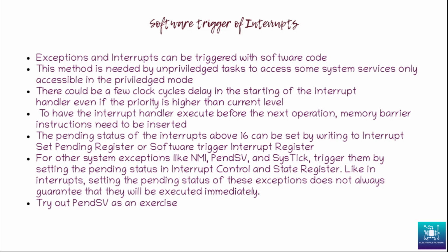When we clear the pipeline, there are no instructions in the pipeline. We'll clear the pipeline through software, so there are no relevant instructions coming in the pipeline. The pipeline will probably be filled with no operation, NOP or something. So the interrupt gets triggered and the ISR is entered even before other instructions are executed on the core.